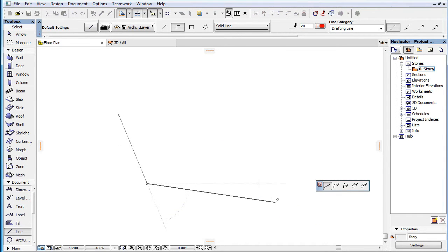When you're inputting a polygonal shape, all edges and endpoints of the input polygon already drawn will be implicitly considered marked as snap references. This way, you can find the extension line of any of these edges and the perpendicular directions to any of these edges from either of their endpoints.